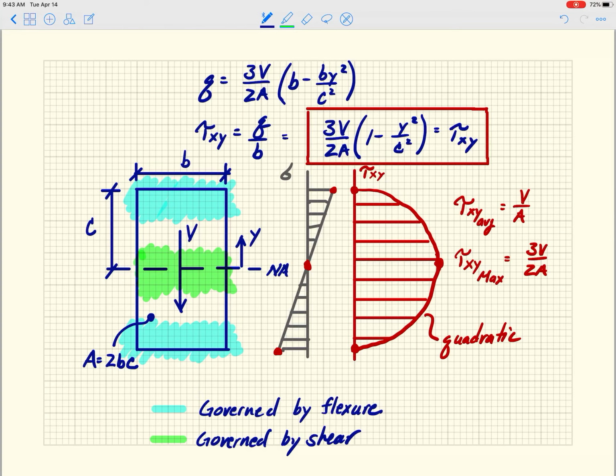I'm not trying to point out that this particular place is definitely going to have more shear stress than bending stress or whatever. Some of this depends on material properties, etc. But the one thing you could say, for a rectangular beam, is that the areas furthest from the neutral axis have a maximum bending stress and 0 shear stress. And the areas close to the neutral axis have 0 bending stress and a maximum shear stress.